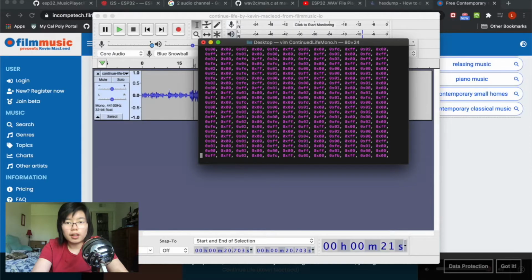Forget most of what I said about amplifiers and ESP32 DACs. All you need to know is that this little breakout board is way better. It uses I2S, or inter-IC sound, meaning that the ESP32 can easily interface with it without having to worry about DACs or amplification, all taken care of. With the breakout board, I could just simply send audio data over from the ESP32, and the board would handle the rest. At least that's how I thought it would go.